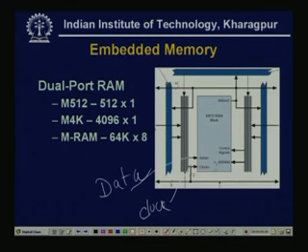Now, this is the data out bit. When I want to access the table or the LUT, this is my data out, or the value of the output function, and these are the address signals, meaning the locations from which I want to get the value, and another is the control signals.